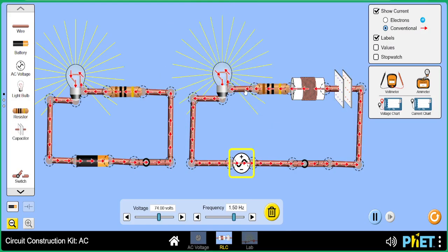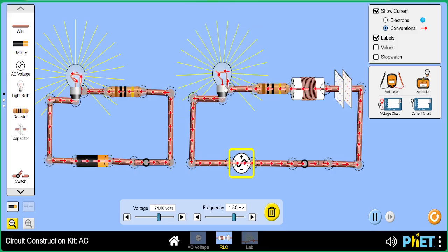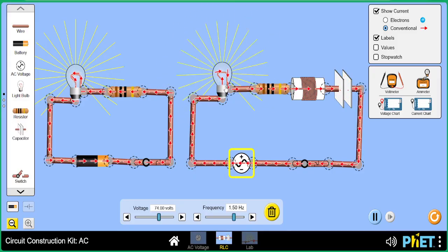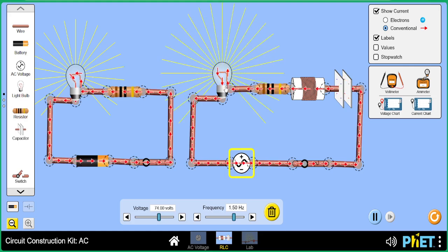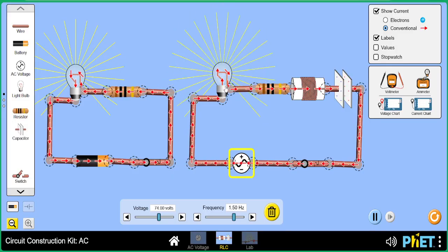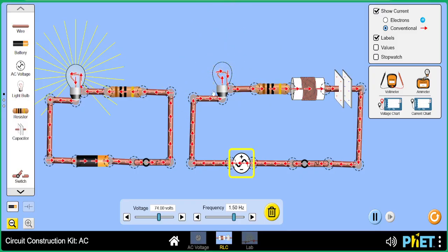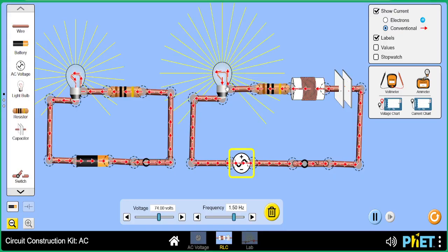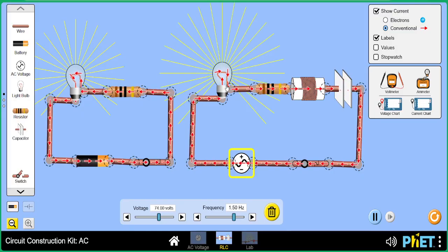Can you notice that? Actually, the bulbs in our homes are AC bulbs and they go on and off. Because the frequency we use in Nigeria is 50 Hz, that means the bulbs go on and off 50 times in 1 second. Frequency means the number of cycles made in 1 second. Often our eyes are tricked into thinking that the bulbs are steady. Meanwhile, in actual sense, they are not. Is that okay?